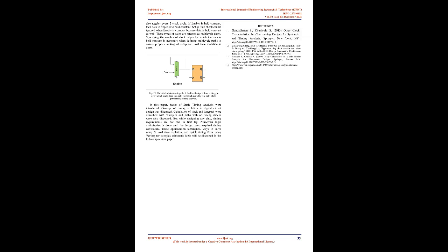It enters a metastable condition if the signal crossing domains toggles during the setup or hold time of the first flop. In a 2 flip-flop synchronizer, the second flop ensures that the signal is stable in the receive domain even if the first flop violates timing. Though the output of the first flop violates timing, the final output of the 2 flip-flop synchronizer circuit is stable. So, this path can also be set as a false path since the design ensures no timing violation occurs.